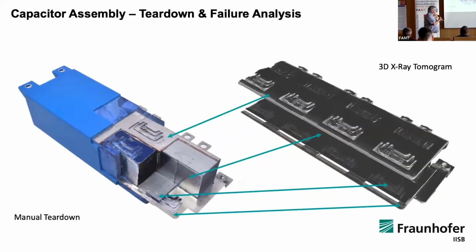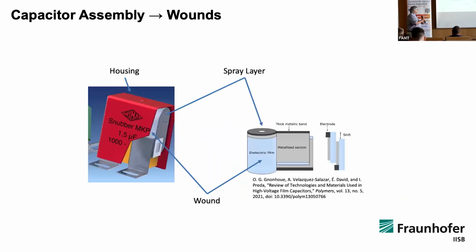And when you look with advanced technologies at such a capacitor, like an X-ray tomogram, the material contrast may be so low that you just see the metal, but not what's inside the device. So mechanical teardown on some occasions is much better than X-ray. Not always true. From the lifetime and analytics side, what we are investigating, for example, is inside such a capacitor,